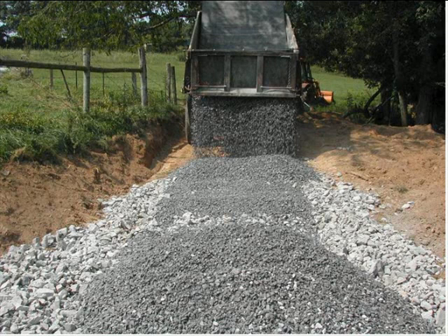So here's a shot of an excavated crossing being backfilled with rock layers composed of about 3 size classes. Once rock is dumped in layers, it can be difficult to mix the material so that the resulting stream bed surface is well graded. At sites where passage is a primary project purpose, it's usually better to mix the backfill at a quarry or staging area, place it into the cut, and blend it laterally to the road approaches and up and down stream bed forms.